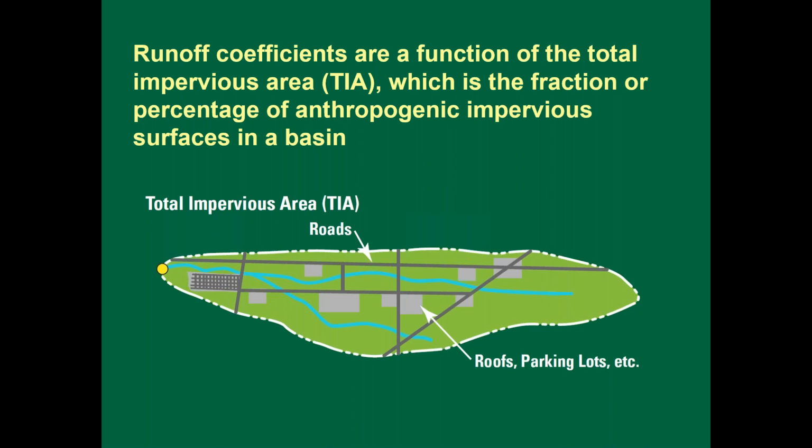SELDM uses the impervious fraction to define the TIA, 0 to 1, of the highway site and upstream basin. We did that because if you're going from 0 to 100, and somebody puts in a 1 thinking they're getting 100, that can be confusing. But if you limit them to the 0 to 1 range, it's harder to misspecify the actual imperviousness you want.